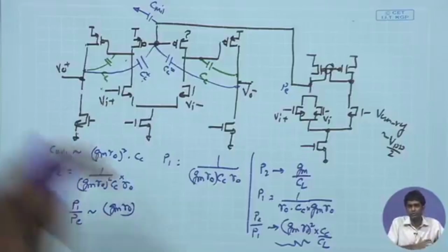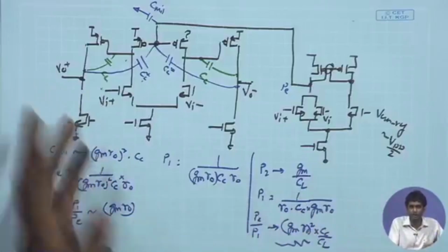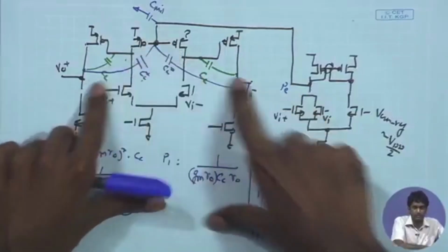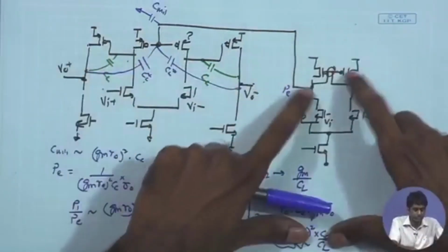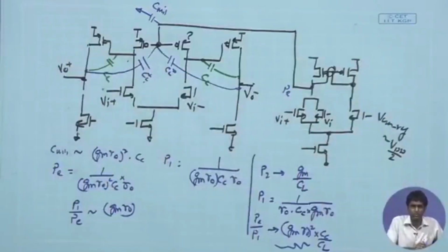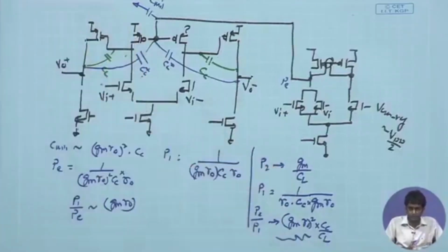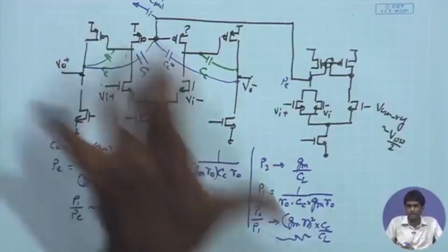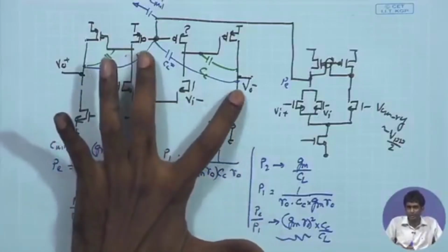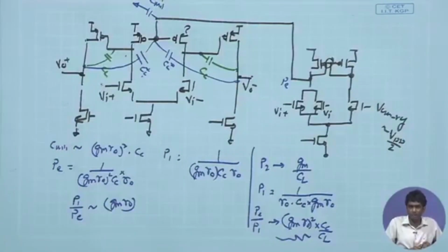So while you are trying to solve or isolate the common mode compensation from the differential compensation with the help of this, hoping to have a better compensation for the common mode, we can see that in the overall picture you can end up messing up the stability of the common mode. So this is another option that can come to mind if you look at where to put the capacitor for the differential and the common mode. So for the common mode, we can say okay, hopefully we can take advantage of this one, but we are seeing some issues. This point is clear.